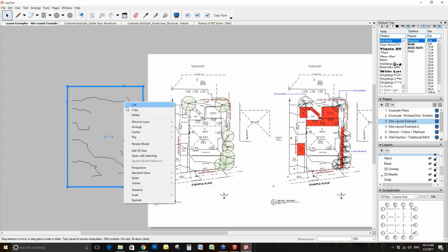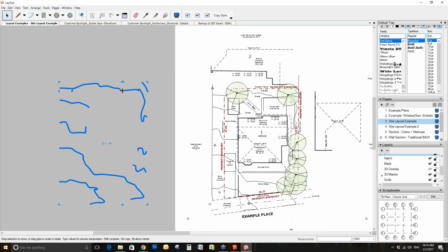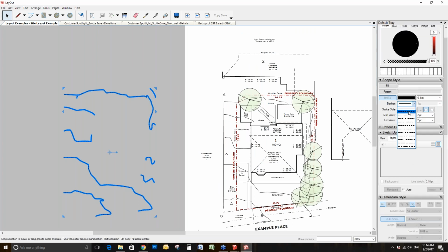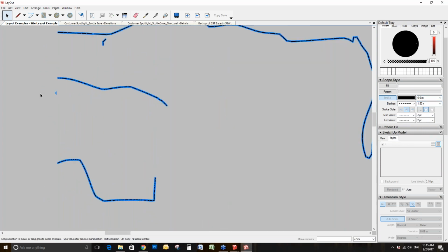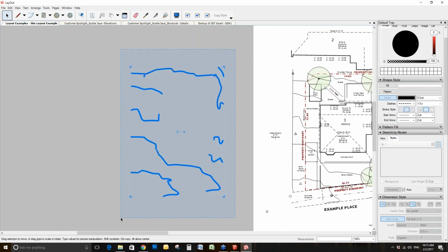I just realized I never actually showed you how to explode. All you need to do is click explode. Once you've pressed explode, you can see that everything's been grouped, so you can just ungroup it, or you can just double click into the group. Now you can select, for example, a whole bunch of your lines. Grab them, and you can say that you want them to be, for example, dashed. You can set the line weight and everything else, however you want it to read, and that's obviously going to update. And then you can simply grab it and group it if you want to.